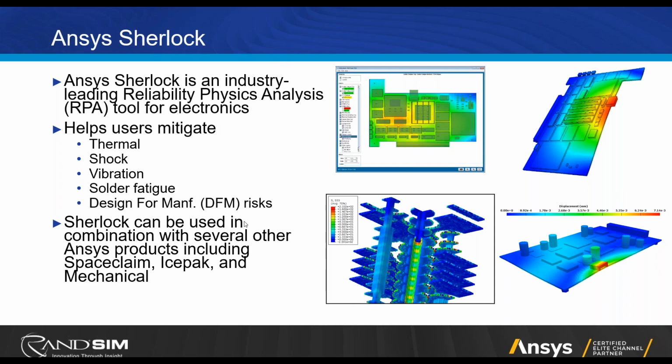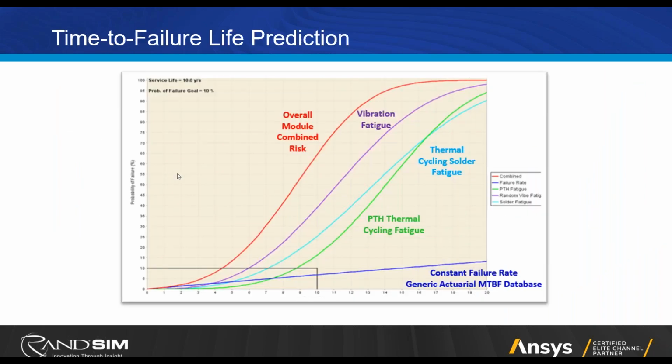Just like IcePak, Sherlock can also be integrated with many other of our simulation tools. This is one of the features of Sherlock, one of the simulations, which I find to be the most useful and just really gives you a great idea, a good bird's eye view of everything that's going on as it pertains to reliability in your device. What we have here is a time to failure prediction. We have the likelihood that the design will fail at any time due to any specific cause.